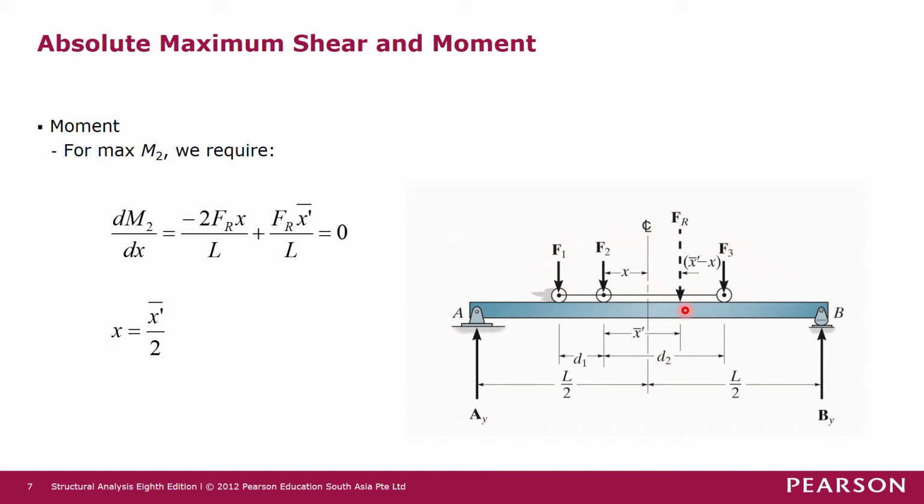And then you select another point. You draw the influence line for the moment again, and then determine the maximum moment due to this system of forces with respect to this point. And then you select another point and repeat the process. It's quite a tedious process. So you have to select a few points on the beam and then draw the influence line for the respective location, and then determine the maximum moment due to this system of forces at each respective point.